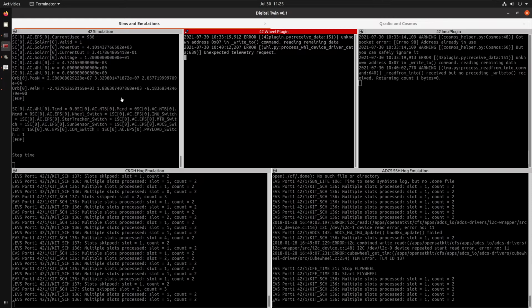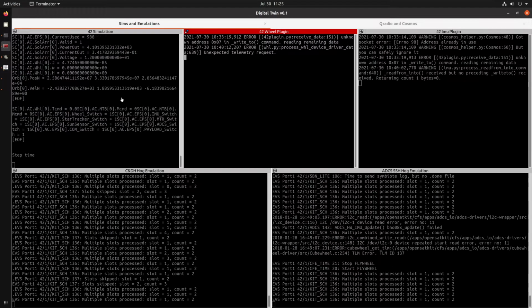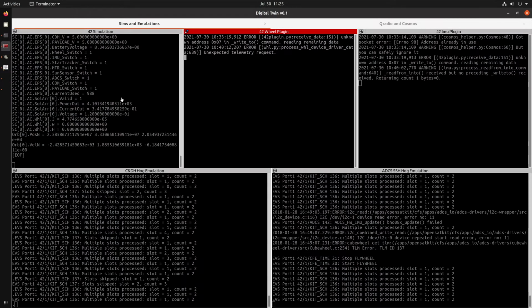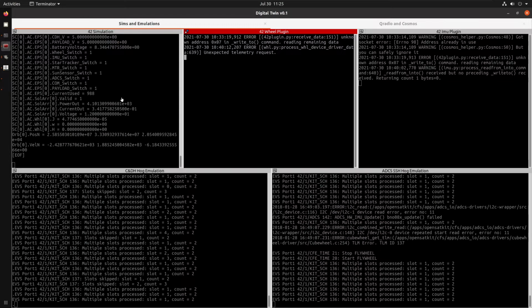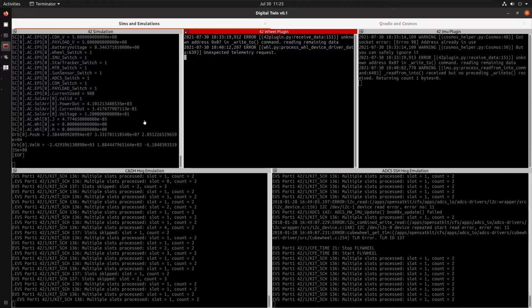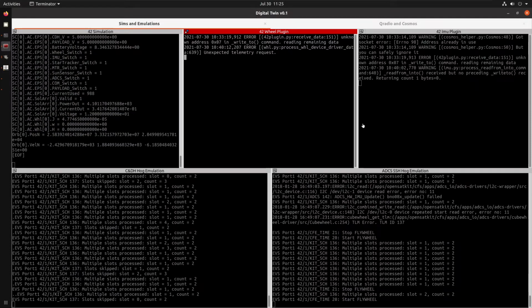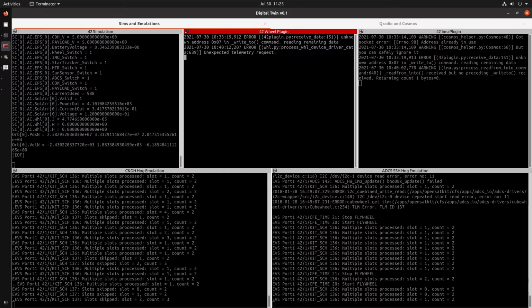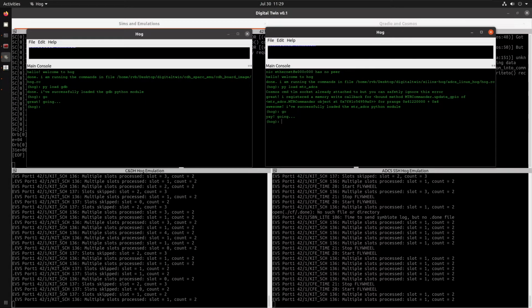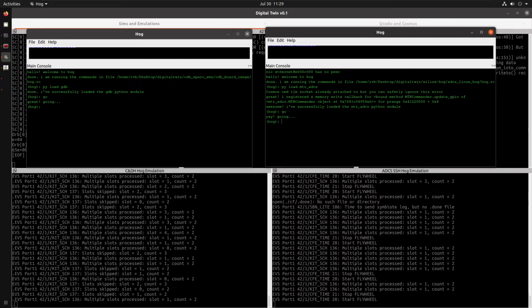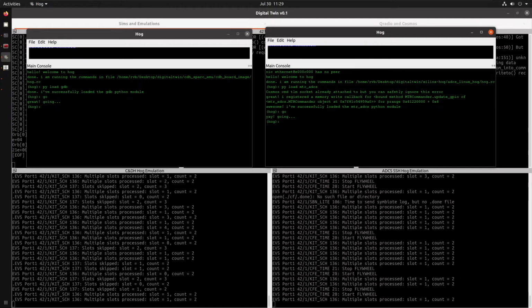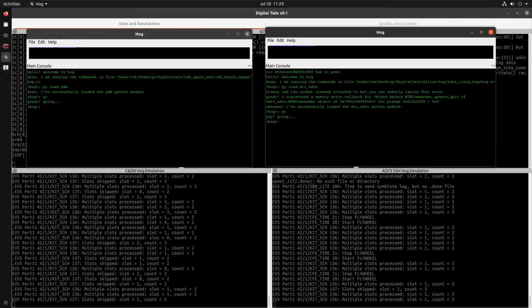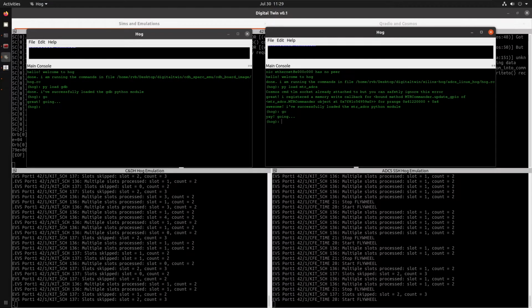At its core, the digital twin is built on top of Cromulence's custom emulation platform, HaG, which is itself built on top of the open source QEMU project. This emulation platform allows the digital twin to emulate the real FlatSat hardware at the instruction and peripheral level. The 2 digital twin HaG instances are used to emulate both the Attitude Determination and Control System, ADCS, and the Command and Data Handling, CNDH.